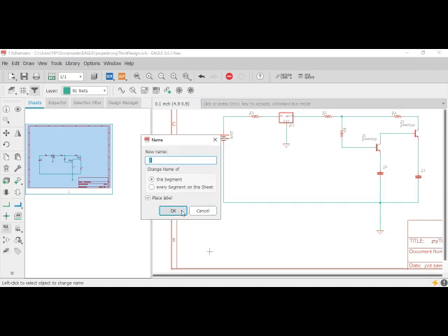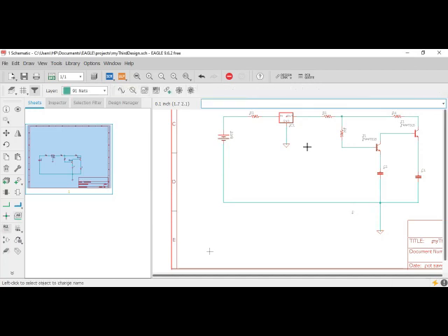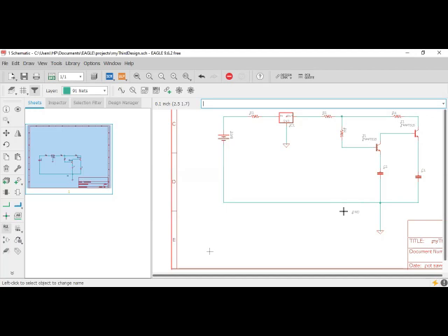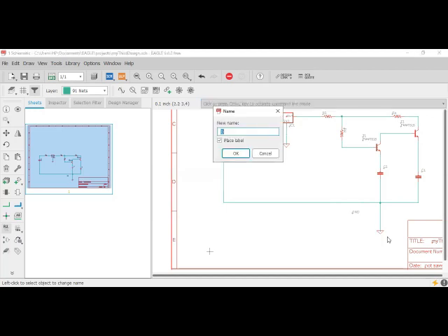So meaning this label and this label are the same, 0 and 0. We've matched them together. So I can change this one to ground, GND. So can you see this is GND? Then I'll come here as well, rename it. If you don't rename it, they are not going to match together. GND as well. Okay, connect 0 and GND.